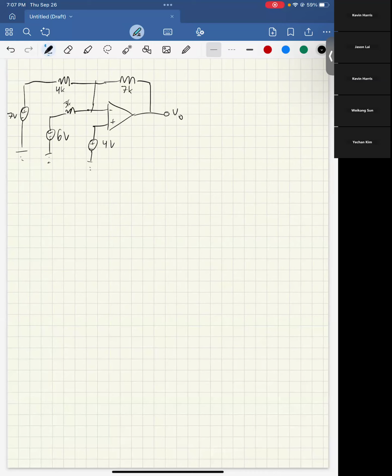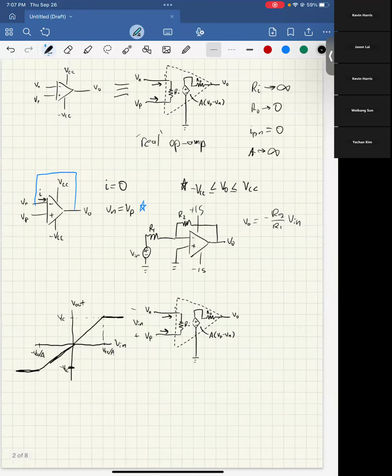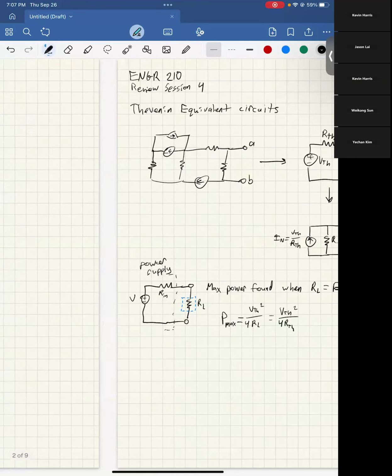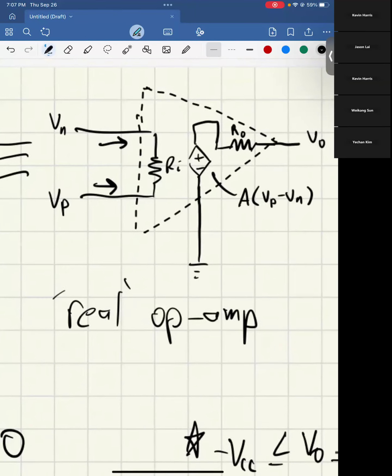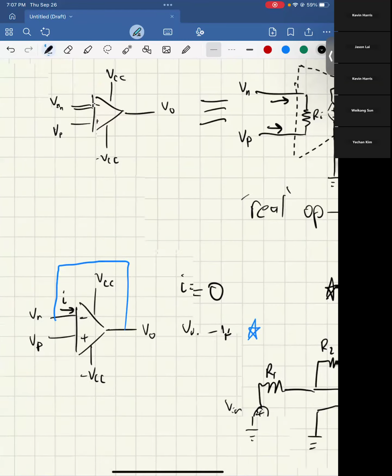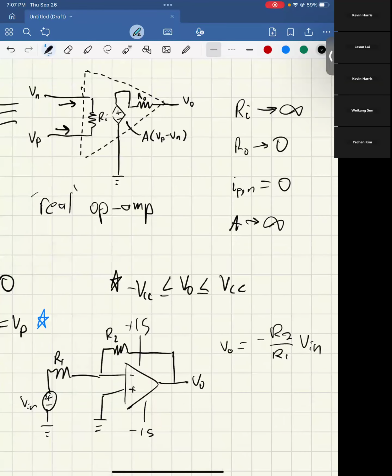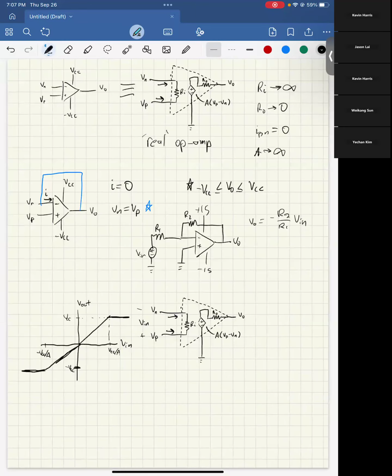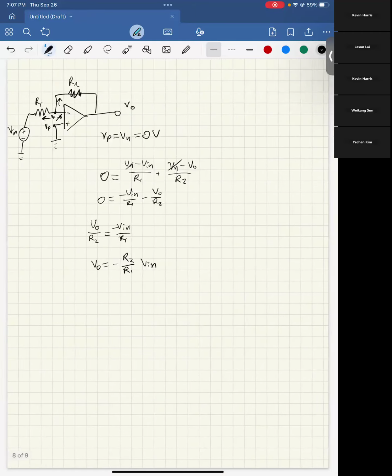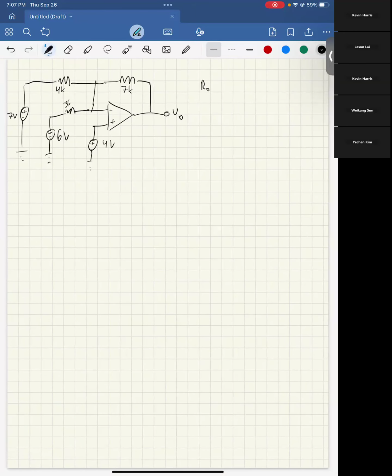And then we have that R out. If you remember from the model I showed at the beginning, oopsies, I didn't mean to make that page, but this is the model we're working with here. We turn this op amp into this. R out is the one going out of it, and then we have Ri, and A as our gain. It's given that Ri equals 500K, a big number. R out equals 5K, a relatively small number. And A, our gain, is 300,000.